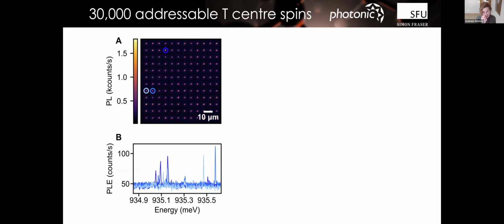And on each of the pucks, we could take a look at their individual luminescence. You could send a laser across them and take a look at what their natural frequency is, because there is going to be some variation depending upon where the center is in the puck and how strained it is, right? But this is a pretty narrow energy range. And it's only slightly broader than what you would expect the natural energy range to be in natural silicon. If you recall one of the earlier slides, natural silicon was this big, broad Gaussian, and then silicon-28 makes it nice and narrow. So that's kind of what we're expecting.